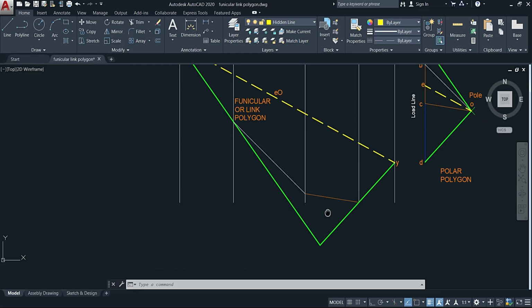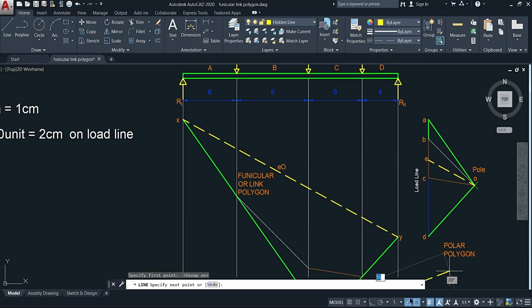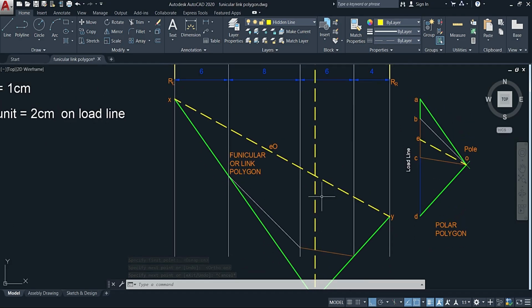Now once you have done so, the next thing that you're going to do is draw a vertical line from where these two lines intersect, that is AO and DO, all the way up, a perfect line, until it touches your free body beam right there. Also something to note, where your BO line and your CO line intersect as well.